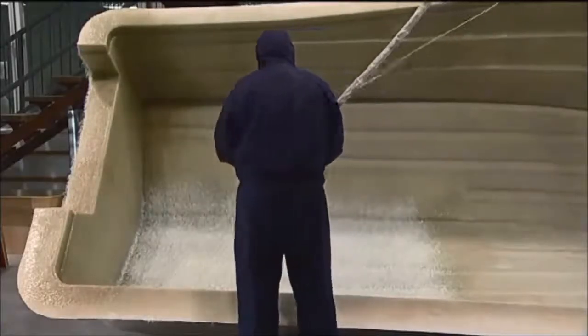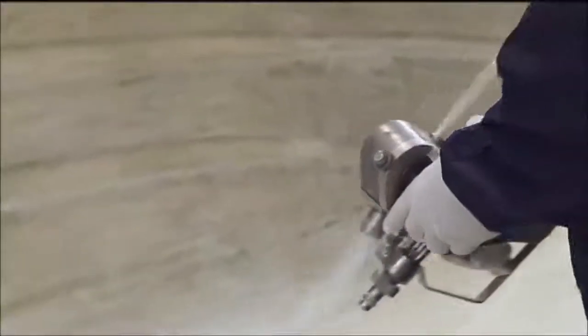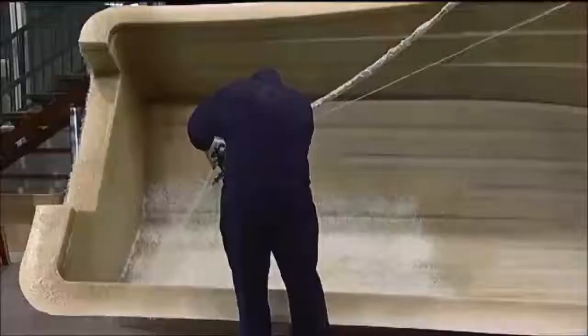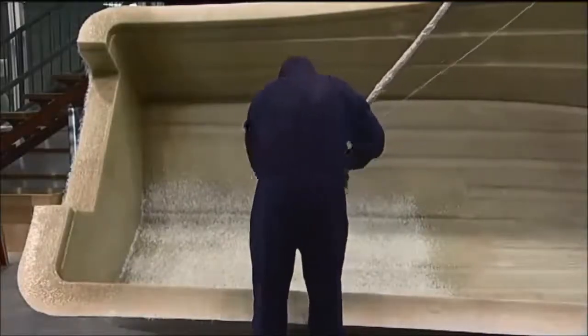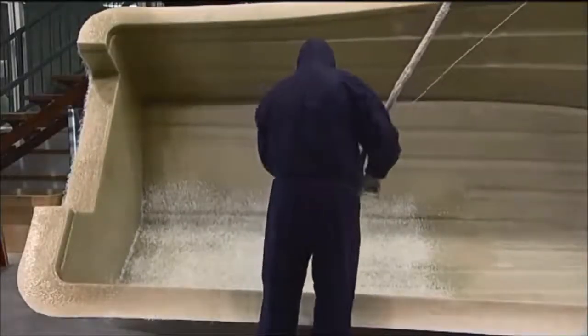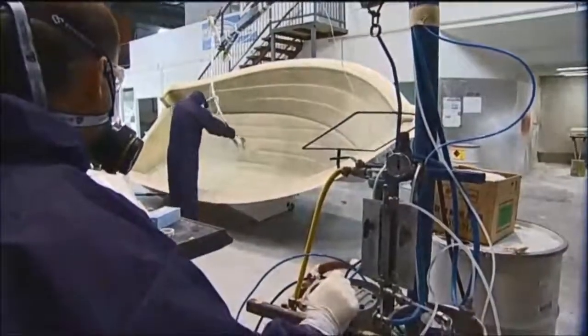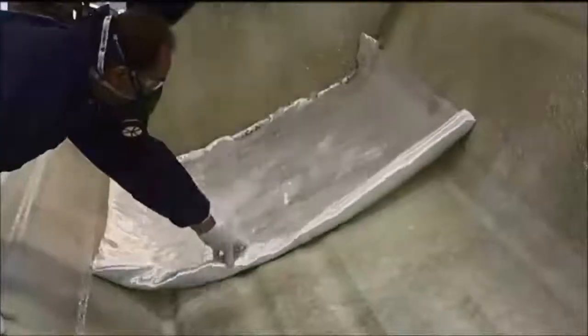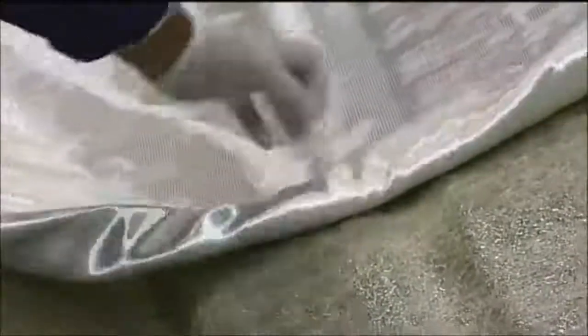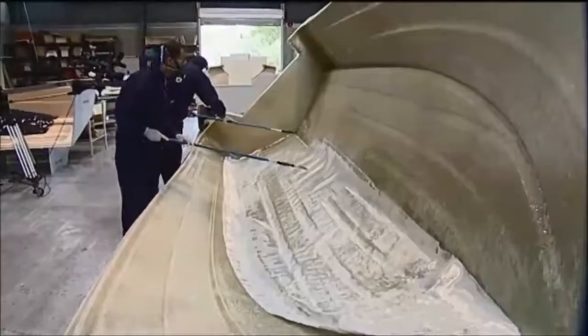The spray-up process is a method in which resin is sprayed onto the mould at the same time as the chopped rovings. The spray gun is moved in a predetermined pattern to create uniform thickness of laminate. Considerable skill is required to control this. The air pressure in the lines to the spray head and chopper are preset within certain limits to regulate the ratio of glass to resin that has to be simultaneously deposited. Additional layers of chopped rovings, woven roving or mat and resin may be added to build up the right component thickness.